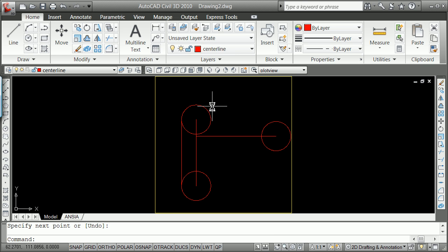This one here is a tangent, tangent, radius, the one on top. So we're going to go here, tangent, tangent, radius. We're going to grab, with no snaps, the inside of that, and then say 56. We're going to trim that, and eventually we'll just erase that out there. Now this last is the ogee, so what I'm most specifically interested in.